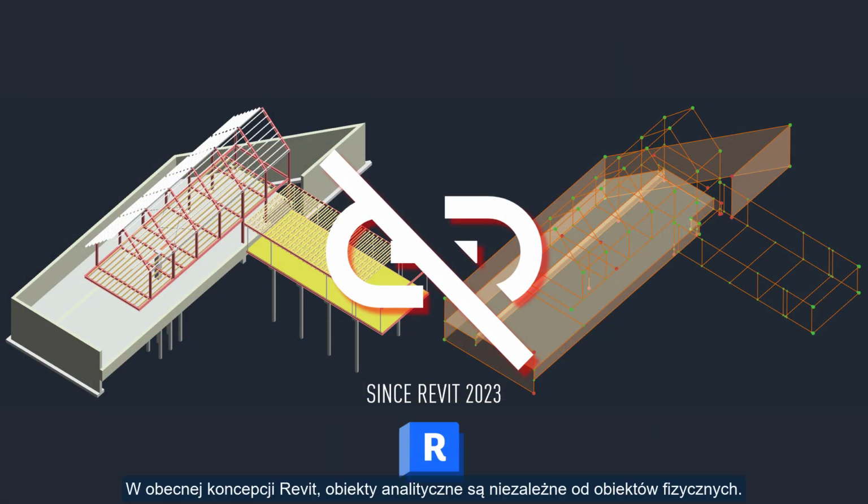In the current Revit concept, analytical objects are independent from physical objects. They are not automatically linked to them, and they don't follow every change in the physical model. The advantage is that we have more flexibility when building the analytical model. In fact, analytical objects can even exist without physical counterparts. This was an important change in Revit 2023. Before that, analytical counterparts were always directly linked to the physical structural objects.